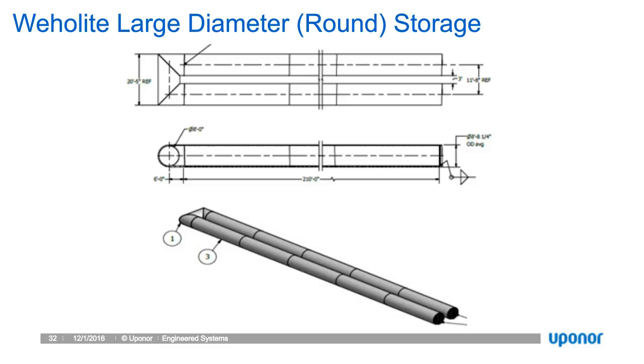Here you can see on the left-hand side of the slide what is referred to as a large diameter header or manifold. There's also the option to do bulkheads, and you'll see in some photos a bulkhead end, and then connecting those sections using a smaller diameter pipe, and that tends to be the more cost-effective approach from a material and fabrication standpoint, to use smaller diameter headers as opposed to larger. But occasionally site conditions and layout configurations require that we squeeze a little bit more storage in the end of the structure, and we can do that with a large diameter header as you see there.